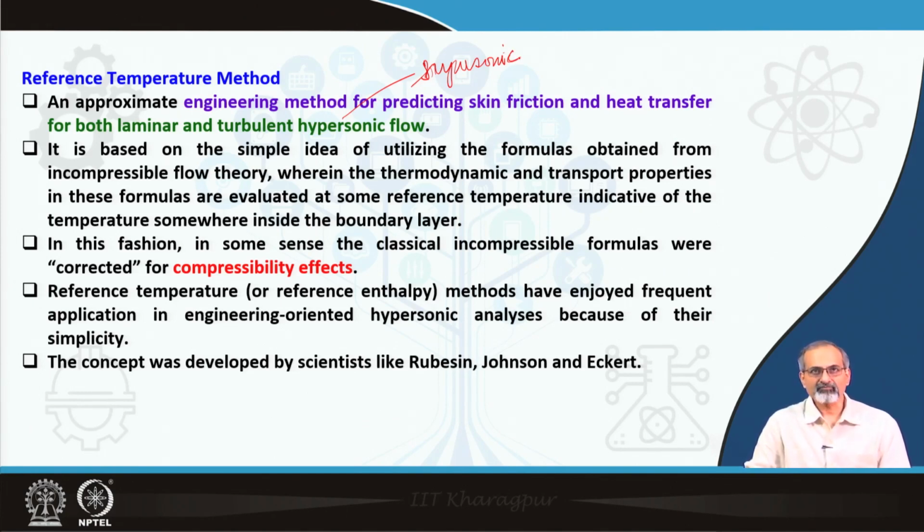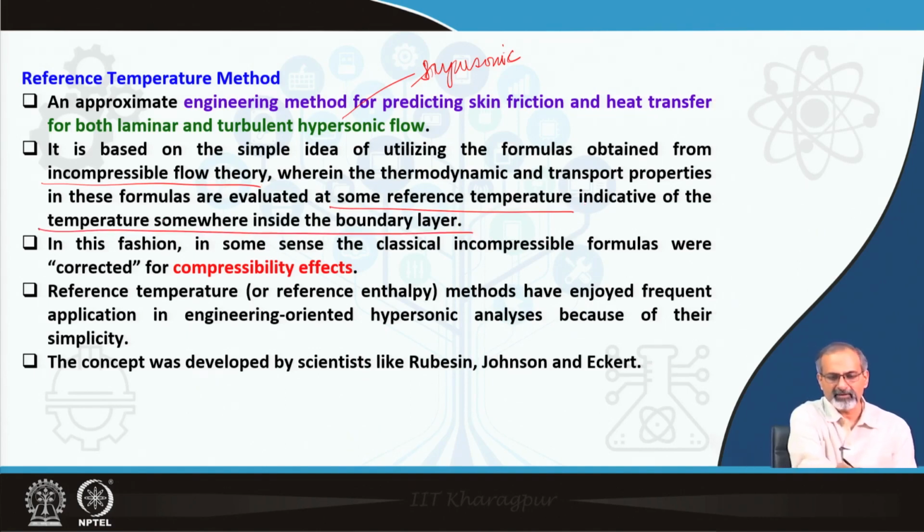It is based on the simple idea of utilizing the formulas obtained from the incompressible flow theory, wherein the thermodynamic and transport properties in these formulas are evaluated at some reference temperature, and that is indicative of the temperature somewhere inside the boundary layer. So, we do not explicitly specify the location within the boundary layer, but we say it is somewhere.